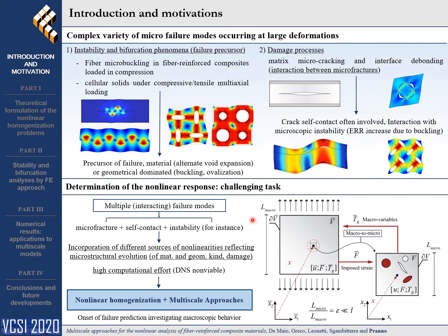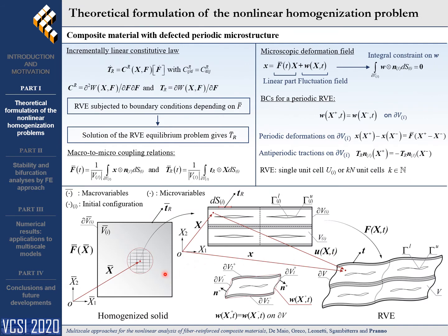The exact determination of their nonlinear response is still a challenging task, and accurate results could be obtained by using full-scale direct numerical simulations, but the associated huge computational effort makes them impractical for real-life application. This situation motivates the necessity to introduce efficient multiscale approaches to predict the onset of failure in these materials, investigating their macroscopic behavior. The composite material is assumed to have a periodic microstructure described by a suitable representative element.